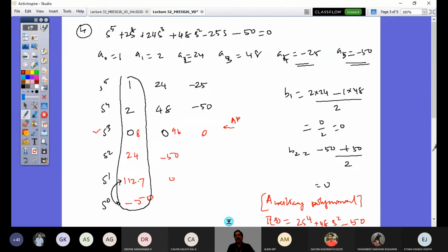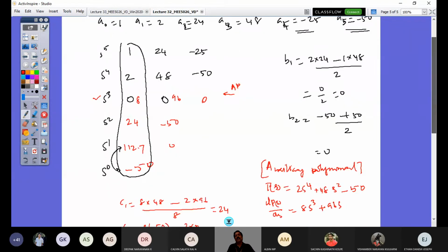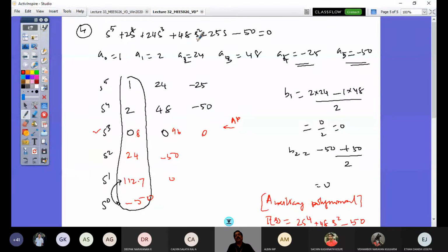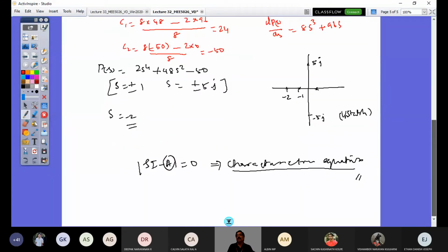And in such cases, you are playing with your numbers fixed, but the coefficients in a physical system are going to have some parameters that influence them. If you play around with varying those parameters, you can make this system stable. So you would be able to have a conditional requirement or parameter limitations and so on. That is a classical example we have seen in our bicycle model. A bicycle model with oversteer tendency can be a stable system when the critical velocity is not reached, right? Till then, I would have my system in the stable state. So that is what we have understood.